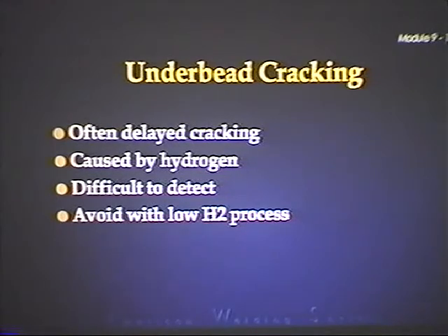And he told me one day that he can tell how tight a job is by the rod control on the job. If he walks through a job and he sees some 7018s laying in a bucket out someplace and some guy's using it, that's bad quality control of the rod. That's bad control. Because how long has that rod been out? How long has it been exposed? When you're out on a job like that and you're welding to code, you have to have a little portable rod oven with you. And you keep your electrodes in that rod oven, and you keep that rod oven plugged in.